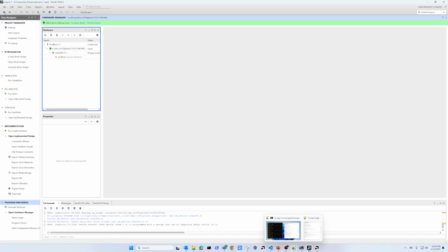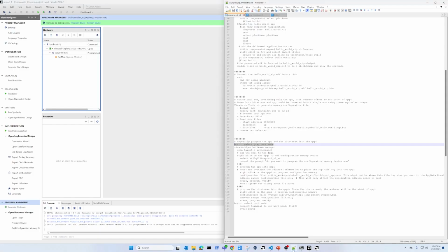I have pin 1 on, I don't see a ref des. J57? Might be J57. Maybe a switch. Either way, there's a 6-pin switch on the board. I have pin 1 set to high on that. The rest are set to off. So hopefully that is what sets it into JTAG mode. Okay, so board, yes, check. Open target, auto connect, yes.